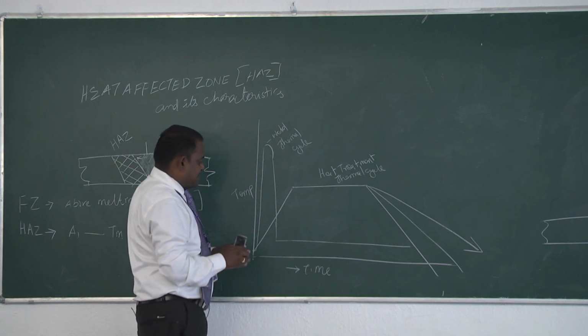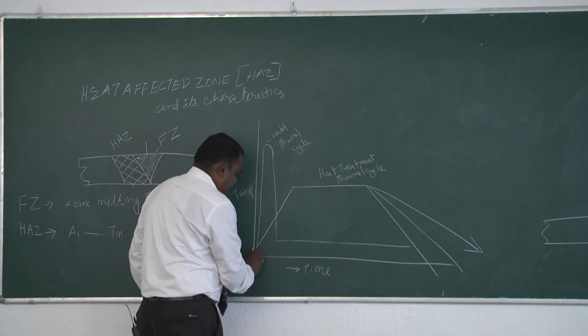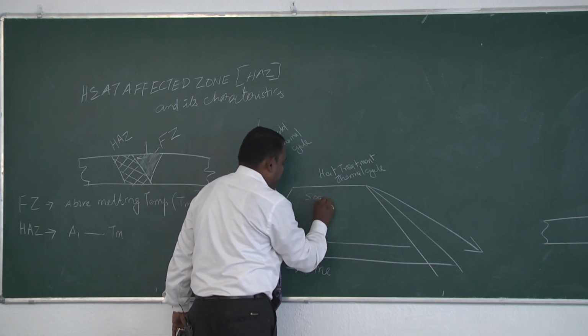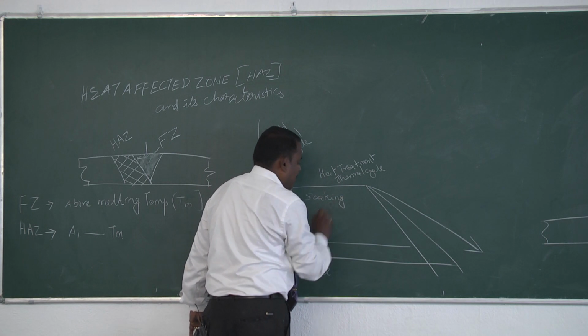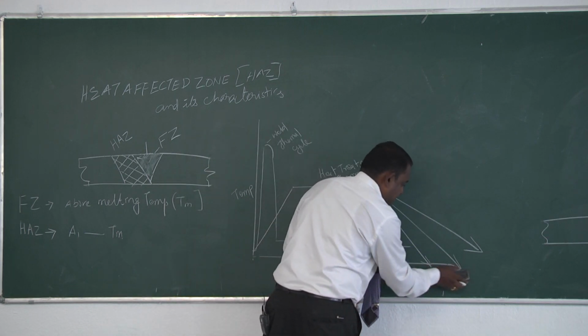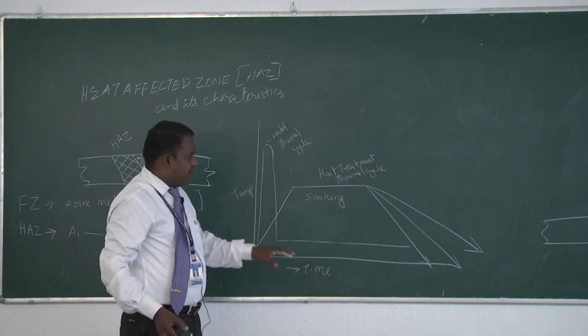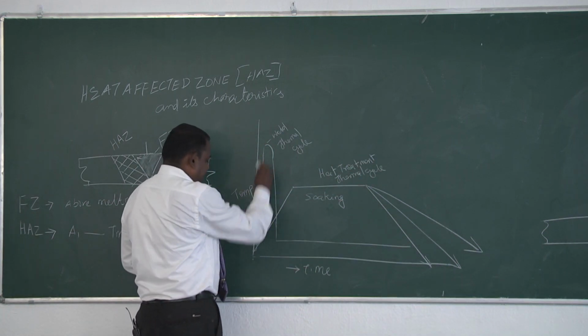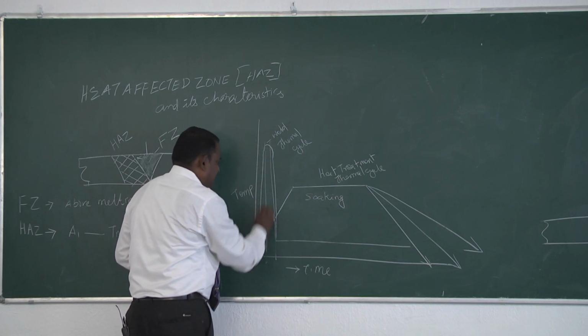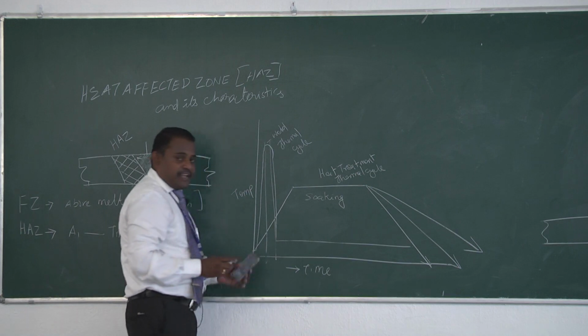One can easily understand that in heat treatment the heating is slow and progressive, with holding for some time, which is called soaking, and cooling at different rates, which decides the type of heat treatment required. Similarly, in welding the heating is rapid, holding is for a small time, and it is cooled to room temperature in very minimum time.